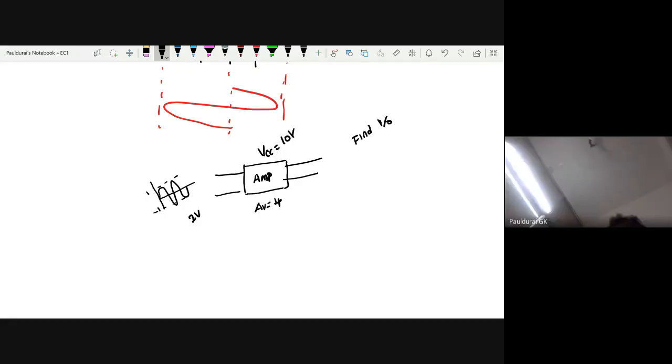8 volts. So Vi, just simply take 2 volt and voltage gain 4. So obviously V out is equal to AV times Vi, that you know, right? Since you know voltage gain is output voltage divided by input voltage. So output voltage is AV times Vi, where AV is 4 and the input is 2, so 8. You are expecting 8 volt, so you will get 8 volt, nothing wrong.